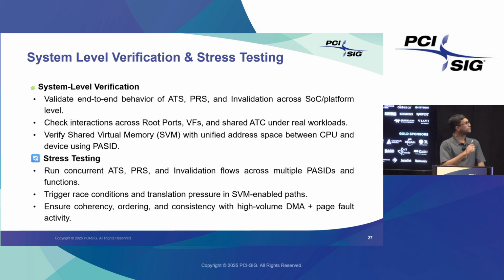Yeah, I think there are some system level scenarios. End-to-end behavior is very important to verify in these three capabilities, because until now we discussed one device and one RC. If you want to have more devices, more PASIDs, mimicking virtual VMs, so many VMs, that is when this system level verification comes into the picture. We can use the same constraints by putting in a multi-dimensional array, using one dimension as requester ID, like device ID. Then we can increase the same setup for multiple devices.